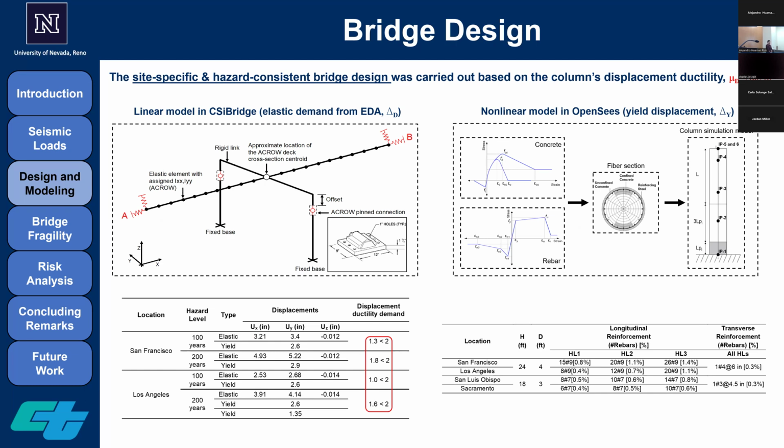for the pounding effect that you mentioned right now, the pounding is typically for bridges that have abutments that are designed to do so. Since these are temporary bridges, and as per communication with Caltrans, there is no such abutment that has the backfill to provide the pounding. Our behavior at the two abutments is simply a linear behavior because of the soil. There is no shear key to prevent unseating. There is no back wall of the abutment to provide pounding effect or even a gap. So that's why the primary nonlinear behavior of such structures is concentrated within the columns.